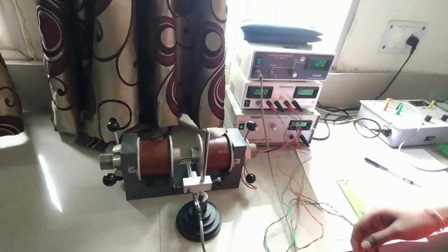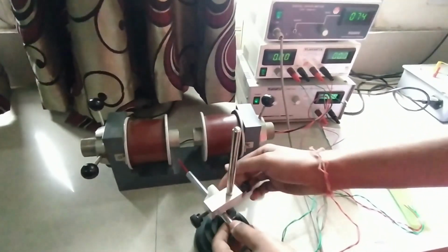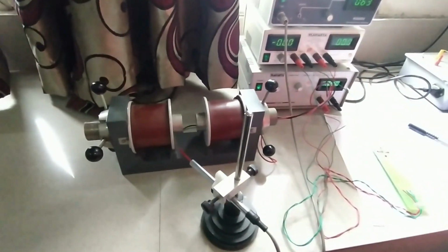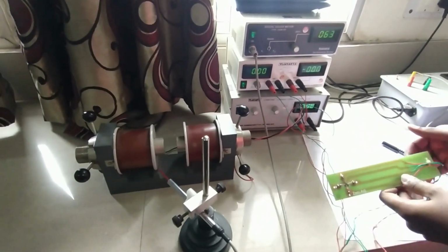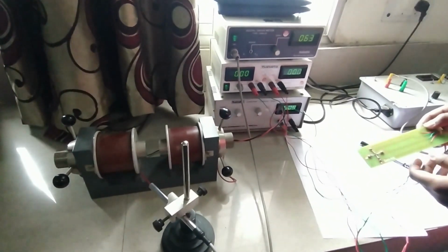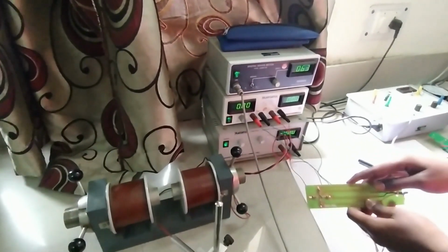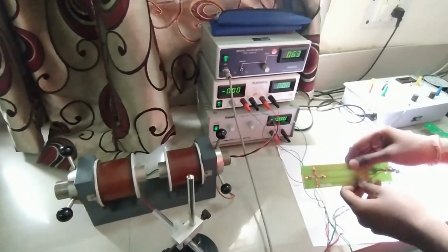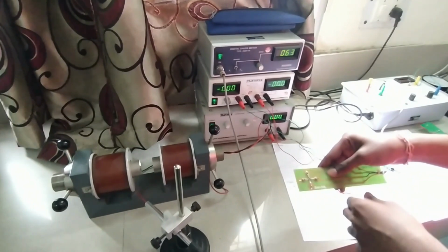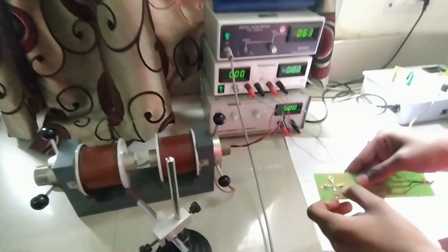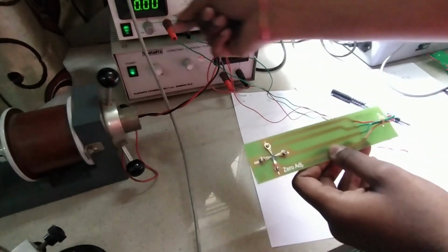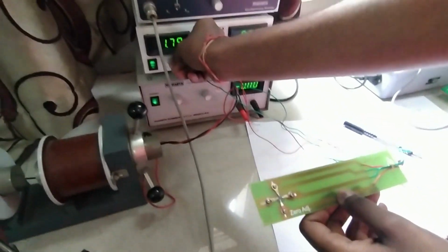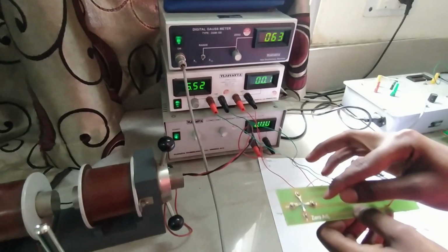For conducting the experiment, we have attached the magnetic sensor to this clamp stand, and now we will attach the sample to it. But before attaching the sample, it's important that we first start with configuring the sample. As you can see, we have 4 probe terminals attached to the sample, and we need to adjust those probes so that when we apply a current to it, in the absence of a magnetic field, the Hall voltage should be 0.